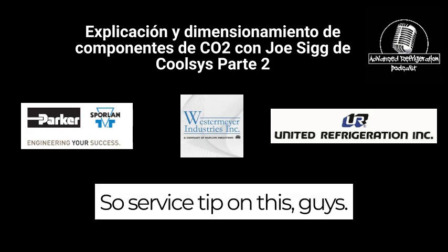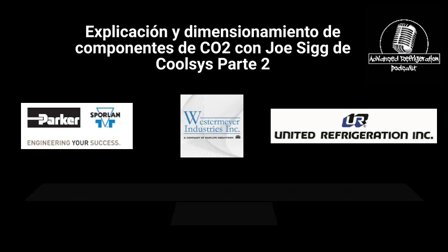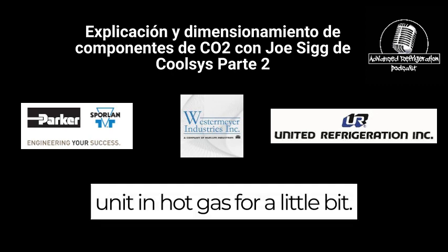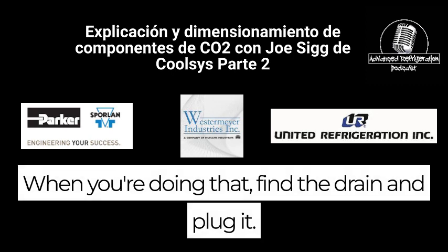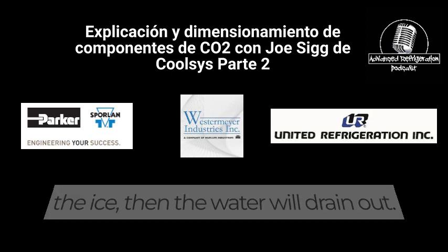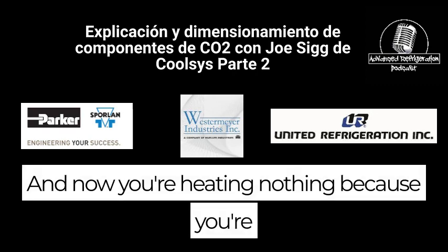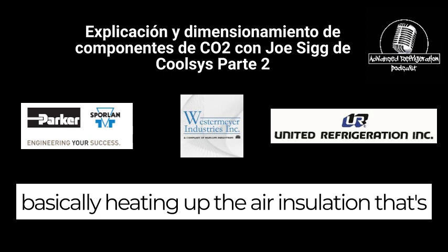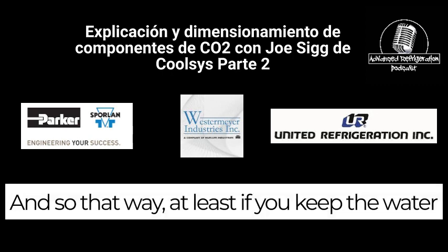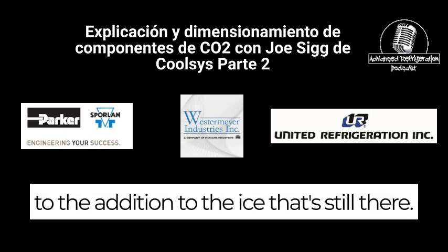So, service tip on this, guys. If you're dealing with this type of system where it's going through the pan first, a lot of times in industrial situations you can leave the unit in hot gas for a little bit. When you're doing that, find the drain and plug it. A lot of times that hot gas will melt all the ice, then the water will drain out, and now you're heating nothing, because you're basically heating the air insulation between the coil and the ice. If you keep the water in there, it can transfer the heat from the coil to the ice that's still there.